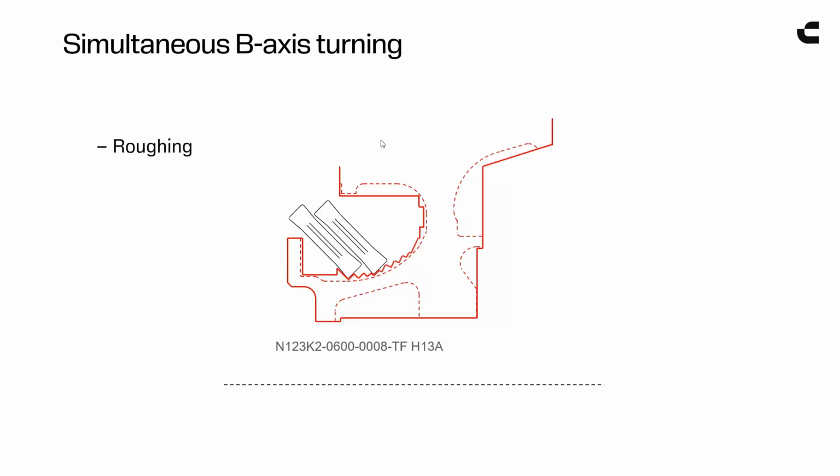So real quick, just as an example, what B-axis turning is not is an all-encompassing solution. You still want to 2-axis turn everywhere you can, then use indexing 3-axis turning to pick out different corners and areas, and then utilize the simultaneous B-axis turning just for the finishing operation. That's my recommendation for most operations. Not unlike 5-axis milling, just because you have a 5-axis milling machine, you actually want to do as much as possible with 2.5-axis milling, and then use 3+2-axis milling, and only then use simultaneous 5-axis milling where needed or advantageous.